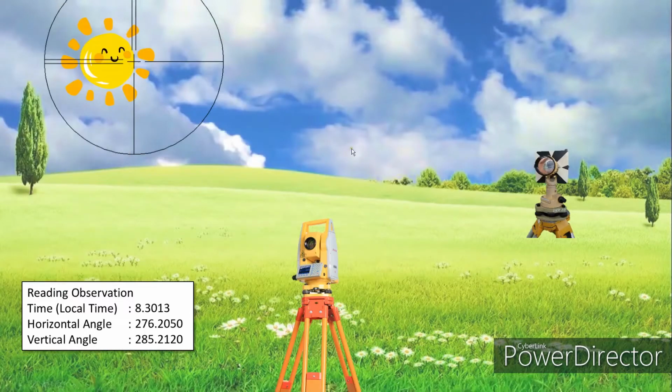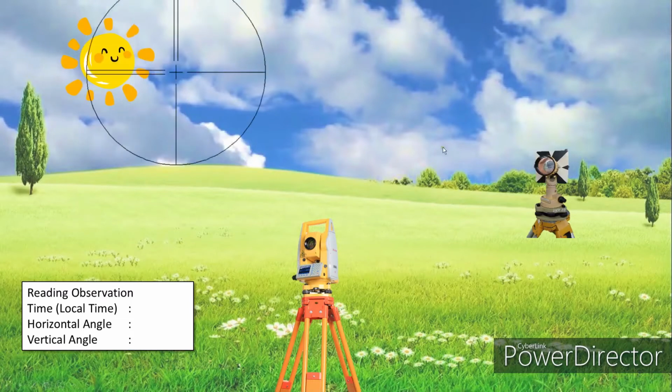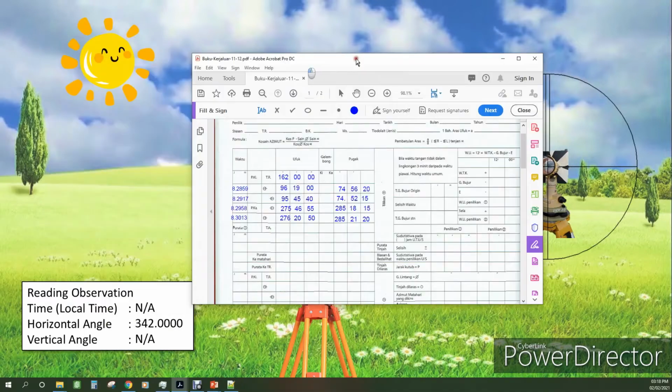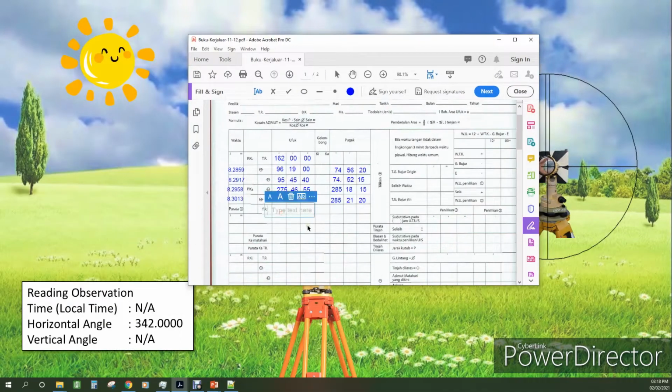Lastly, we turn our total station back to our back side, which is the reference mark. We have a horizontal angle reading of 342 degrees.